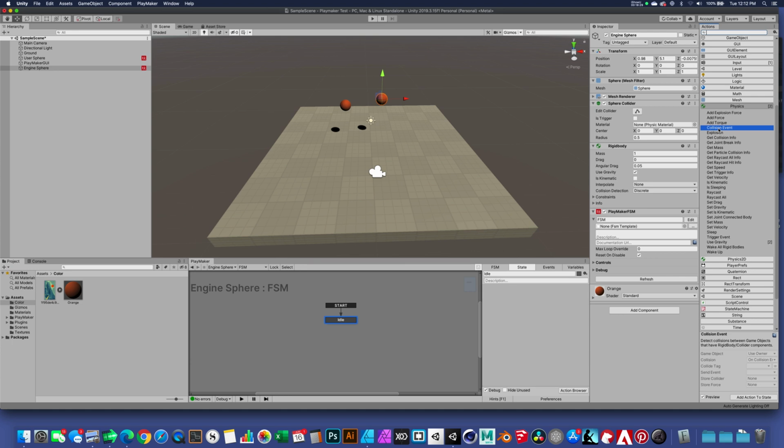So when you made your Gravity Lab project and all these objects are bouncing around, every time an object gets hit by something or hits the ground or falls over, it generates a collision event. So what we're going to do is with our first state, our idle state selected, I'm going to double click on collision event. And we're going to build a very simple scenario that causes something to happen to the sphere when it hits the ground.